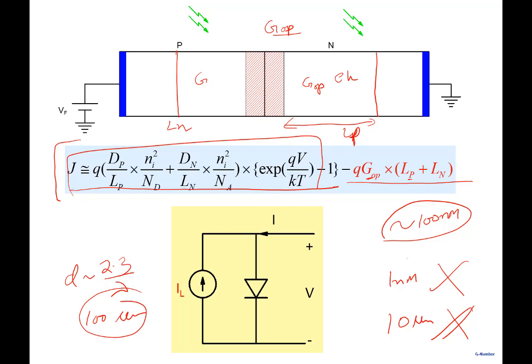here. The electron is already in a majority n-type layer here. So the difficulty is the problem of the hole, because what is going to happen? The hole is there in the midst of all the electrons, a large number of electrons. If you look at this electron hole pair in this n region, the hole is in the midst of all these electrons. So the hole has to survive. And where does it have to go? The hole has to go towards the anode. So the hole has to move towards like this, go in that particular direction. The hole has to go here.